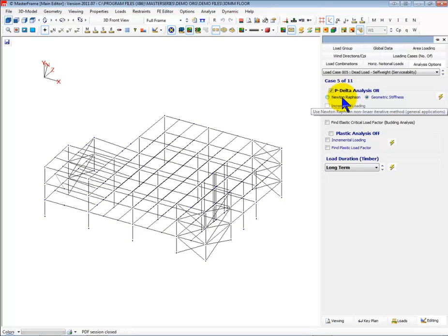What you must remember with that is that we are using large P-delta, so we're just concentrating on the nodes. If you wanted to know the additional deflections at mid-span of columns, etc., you would be advised to apply a few additional nodes along the members to actually obtain those values. But certainly everything that's analysed will be given out to you as deflections. We also have the ability nowadays to do plastic analysis on the frames, and I believe Martin talked on that in one of his latest webinars. We'll probably put that into the notes as to where that's about.